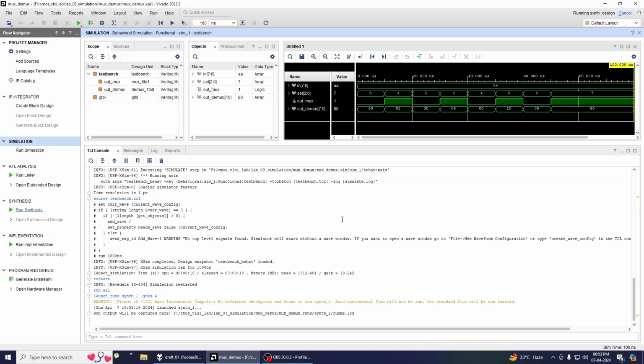In the Xilinx synthesis process, your design code is transformed into a gate-level schematic, optimizing for performance and resource utilization. First, the process reads and interprets your HDL, hardware description language, files, analyzing the design's structure and functionality. Next, it optimizes the design by reducing complexity and improving speed, ensuring it fits within the target FPGA architecture. Finally, the synthesized design is mapped to the specific logic elements of the FPGA, ready for further simulation and eventual implementation on the hardware itself.